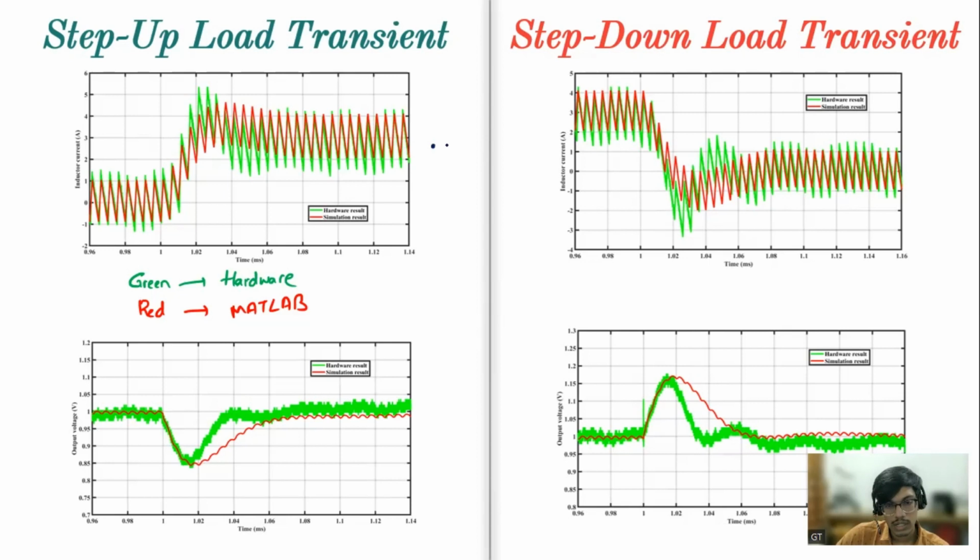So what this .csv file means, it will save the quantized data. So it will be saving multiple data points taken at that clock. It depends upon the oscilloscope how many samples it will take per second. Accordingly, it will take that sample, and this can be opened using an Excel sheet.